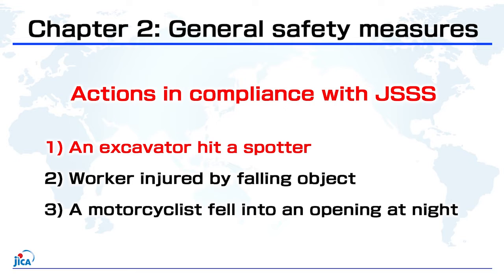The contractor must place spotters to prevent the entry of unauthorized persons at all times during the work, effectively inform its personnel and the general public, including road users and pedestrians, and protect them from accidents.